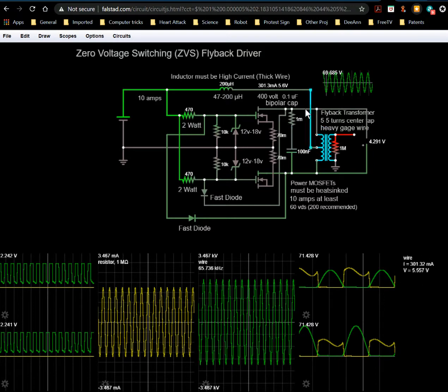Okay, you get current flowing through there, right? But you can kind of look at it as the same current is actually being induced into this circuit too, so you can look at it as whatever 24 volts you have here is doubled here. So this is 24 volts too, and it's in the same direction, so it's basically 48 volts.